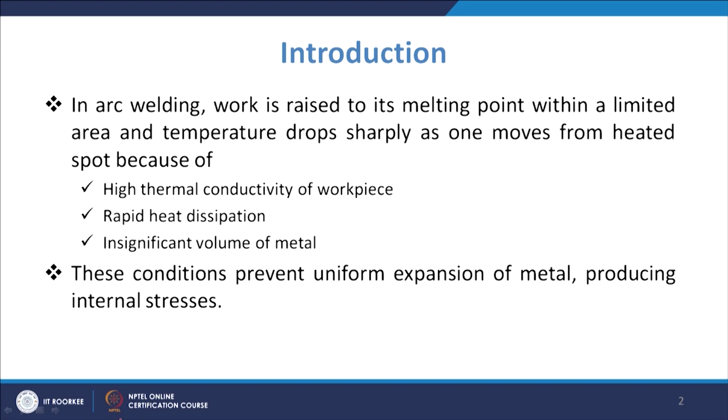If you talk about casting, where you have a large volume of metal, in this case you have a very small metal pool which is getting cooled. So, that volume is also smaller, then you have rapid heat dissipation, and also the heat conductivity on the sides is higher.